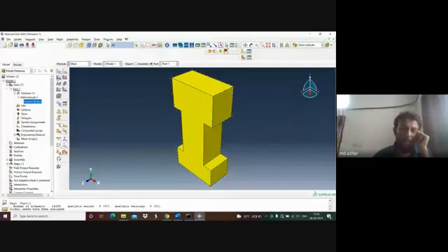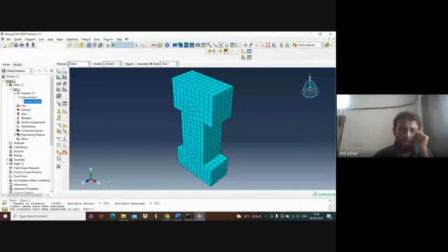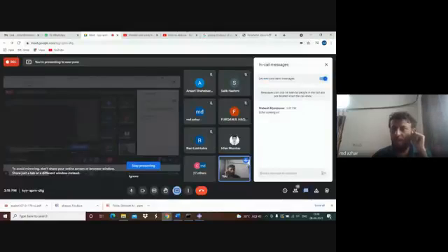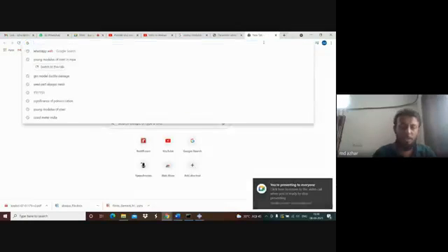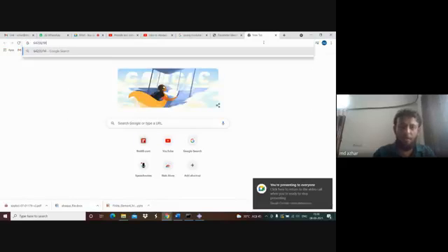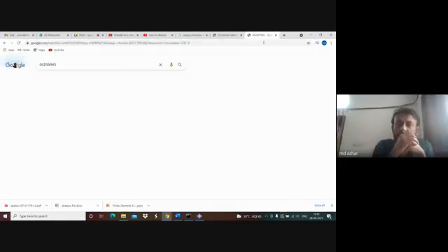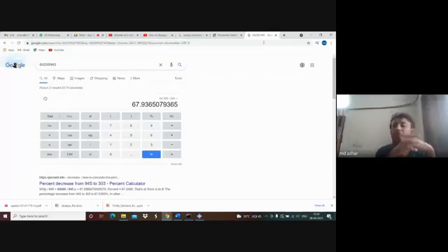Apply, okay, select, yes, this is the mesh. And now let us just go to the verify part. Now you can see this 945 elements, and over here 64,200 elements. So just try to understand in mathematical terms: 64,200 divided by 945. What is the significance of it? You can speed up your simulation 67 times.